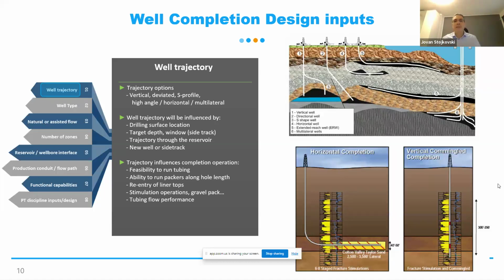So, a very important segment. If you go further, if you have a horizontal, extended reach, or multilateral well, as you can predict, this becomes more complex in terms of completion: how we will interact with the reservoir, and which kind of tools we can put. We will run a lower completion to complete the horizontal section and then come with the upper completion connected, and so on.